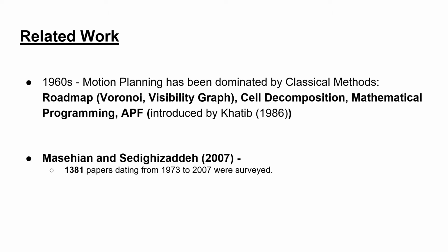The artificial potential field method works by establishing an attractive potential field force around the goal point, as well as establishing a repulsive potential field force around the obstacles. Both of these fields together make up the total potential field, which is named artificial potential field.